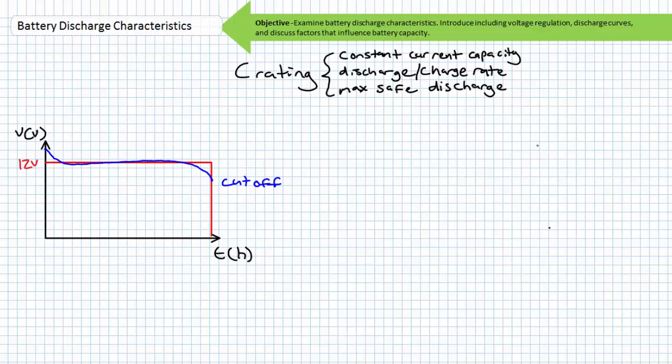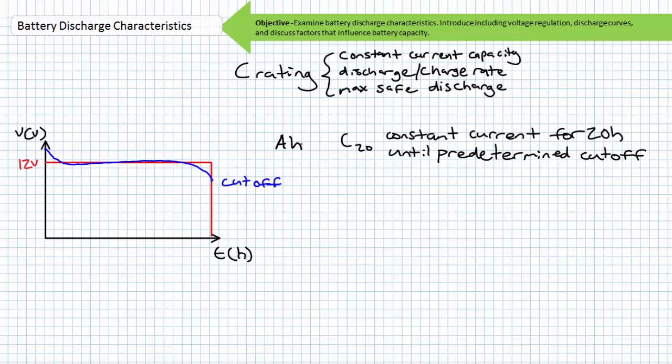It is for this reason most batteries' nominal energy capacity in units of amp hours is expressed at the same rate, placing every battery on the same playing field, though as we'll soon learn, this isn't always the case. A C20 rating is the capacity of the battery in amp hours as if it delivered constant current for a period of 20 hours.